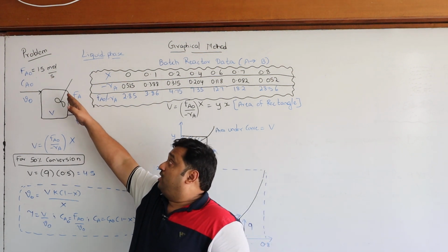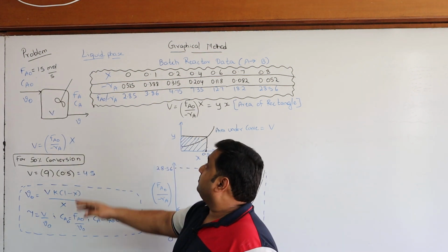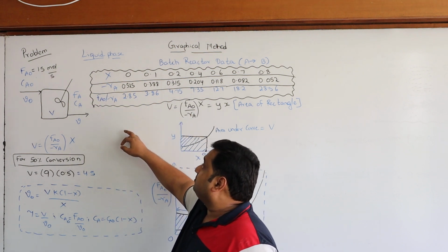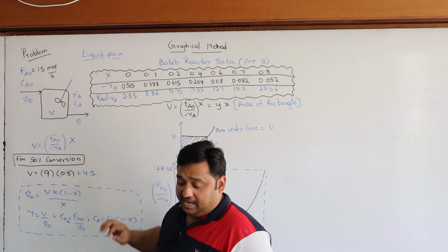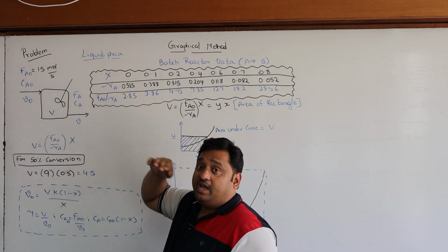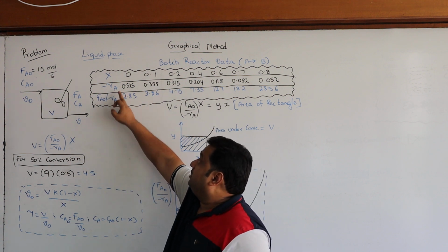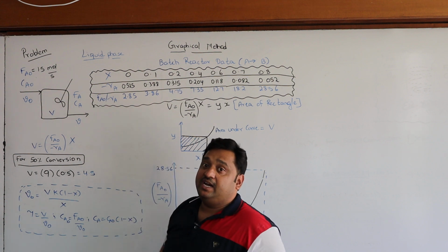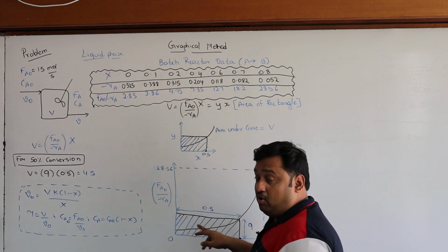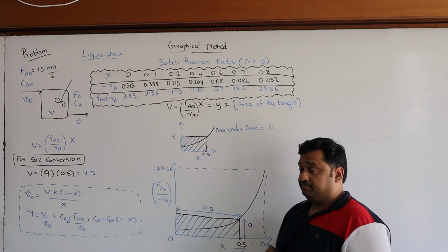I know 1.5 mole per second and I know the minus Ra data, so I know 1 by minus Ra and I can get Fa0 by minus Ra. If I do that, I get the X data and the Fa0 by minus Ra data. Then I have some data points, and through these data points I can connect a line to all of them. That is the black line.